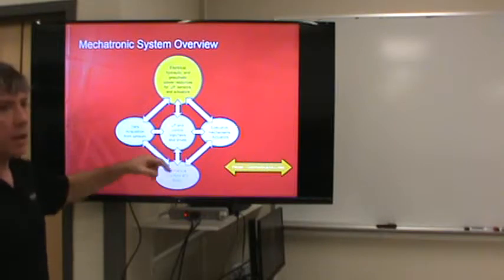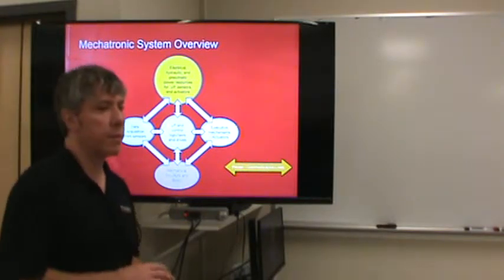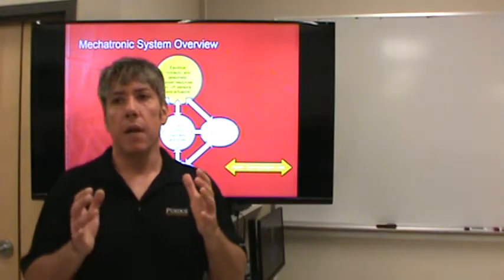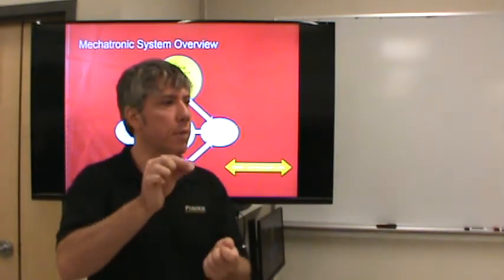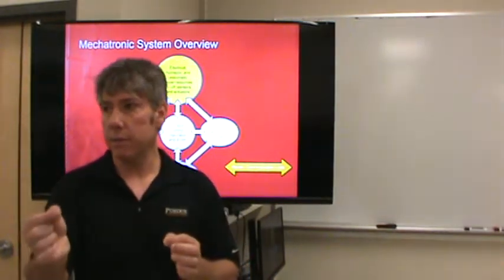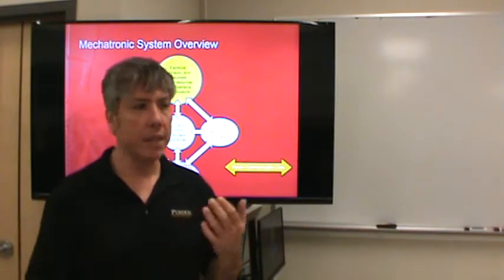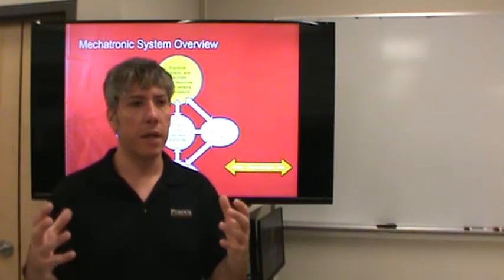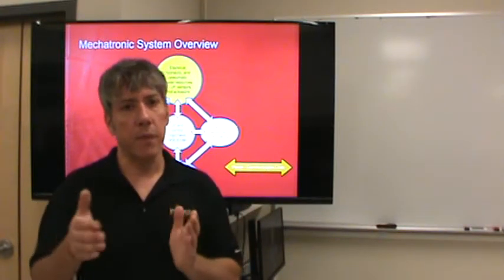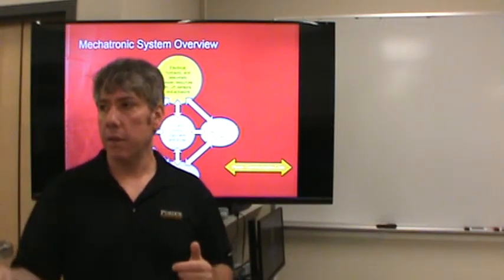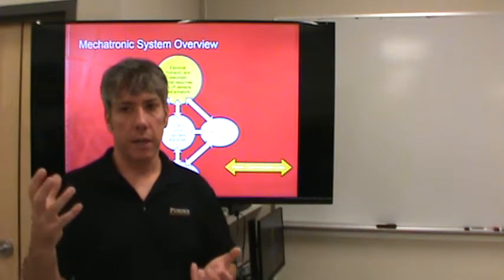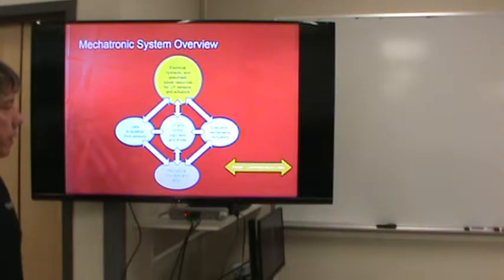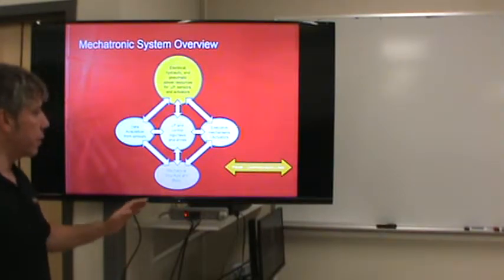The drives, I don't know how to describe this very easily. You'll understand it better as we go through the course, but basically you can't take an Arduino's output pin and connect it to anything directly, for the most part. It can drive an LED, which is a very small power draw, but you can't, for example, turn on a large motor with an Arduino directly. You have to have something in between the motor and the Arduino in order to amplify the effect of the Arduino. If you've used Arduino, you understand this. If not, you'll understand it soon.